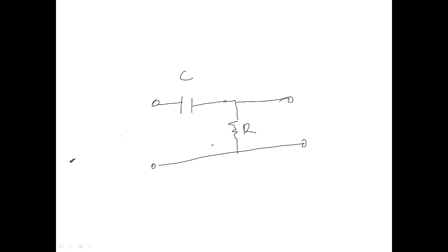Now while giving low frequency, what will happen? You will check it. Here I am assuming this is the high pass filter, just a capacitor and a resistor. By using this, we can stop other low frequency noise signals and allow only high frequency signals. This is the resistance and this is the capacitance. So I am giving again the input, now a low frequency F. I am assuming, just as an assumption, zero frequency for this input.